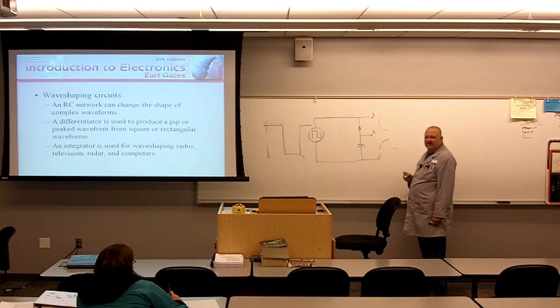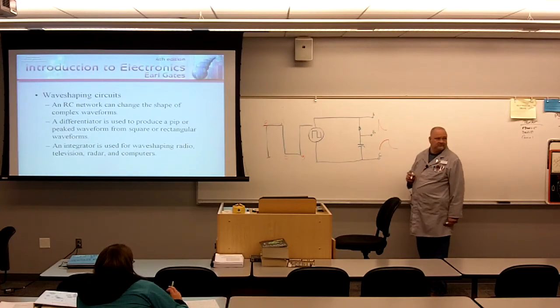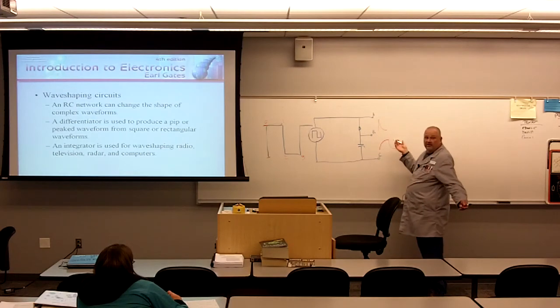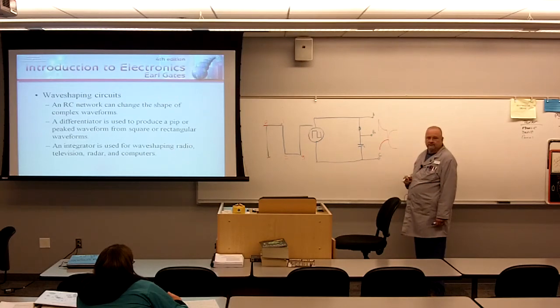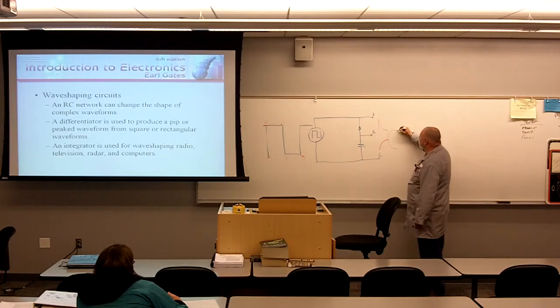When it discharges, where's it going to discharge into? It's going to discharge through the resistor, the only other component in the circuit. So it's going to create POW, a negative voltage, opposite of the force that originally created it, and then that voltage is basically going to go to 0. Make sense? The next square wave pulse comes in, POW, voltage shoots up, a little bit high, a little bit excited there, right? And it's going to come down.